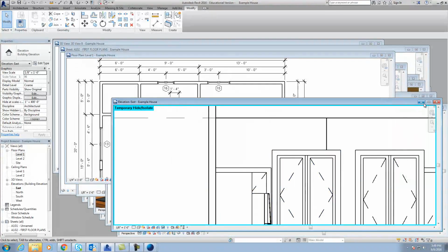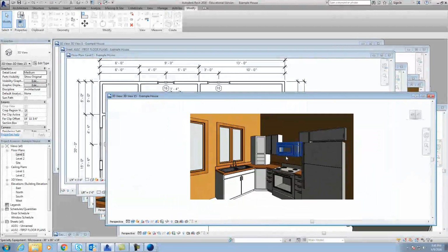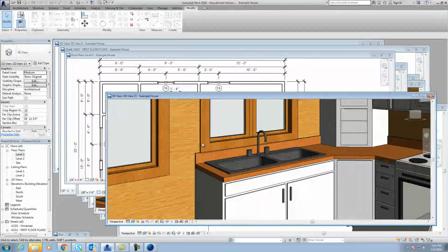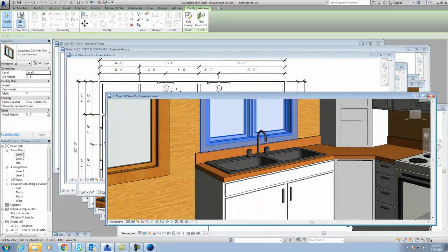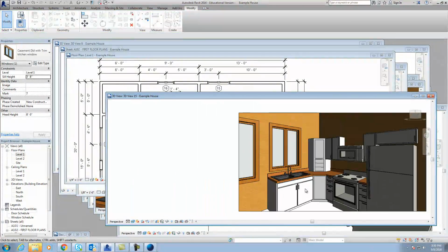And you can see it right here. You see how the window fits nicely, and looks like the trim's going to be hitting. So I'd grab that again, and the sill height, I'd move the sill height up 2 inches, and then to line it up, we need to make the window 2 inches smaller, which was 4.4. And then outside of the house, it would look nice and even.